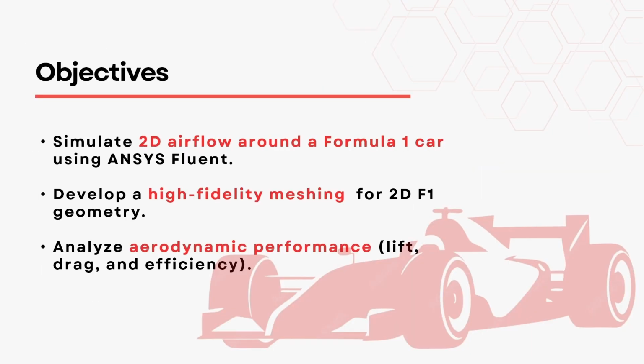My objective in this project is to simulate 2D airflow around an F1 car, develop a high quality mesh, and analyze drag, lift, and aerodynamic efficiency. Also, I will be analyzing two different meshes, one finer and the other not that fine, to see how the result changes. The F1 car model I will be designing in SolidWorks and then exporting to Design Modeler in ANSYS Fluent.